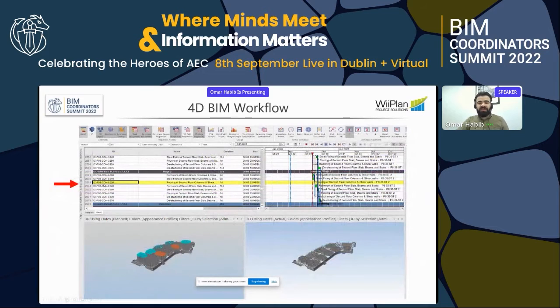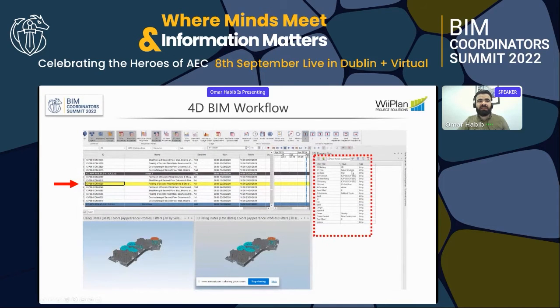You have a standard naming convention that the planning department works on, and you have a standard naming convention for the BIM model, and both should follow the same standard. After doing that, the information for the activity ID can be inserted immediately using any 4D planning tool, like Synchro, like Pixel Manager, like Fuzor, any kind of 4D planning tools. The ID for every stage, formwork, steel fixing, pouring level, everything should be inserted inside the 3D model itself.